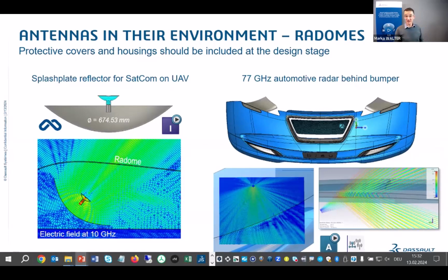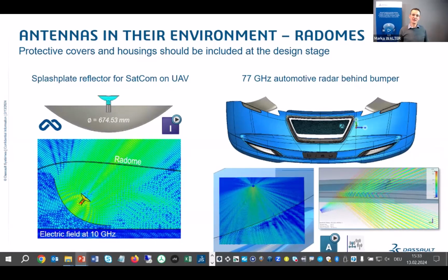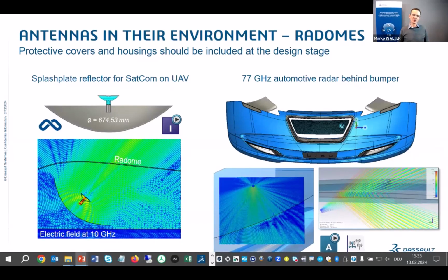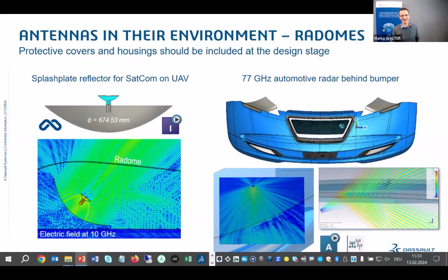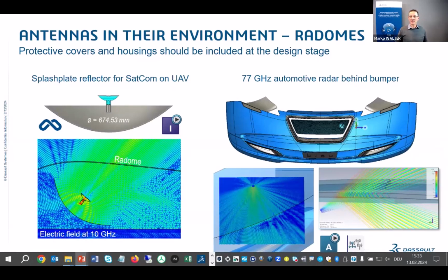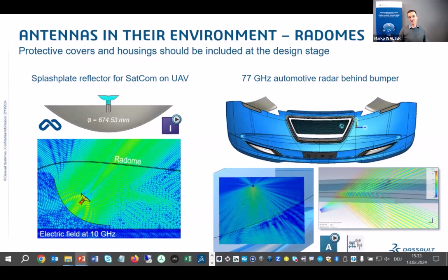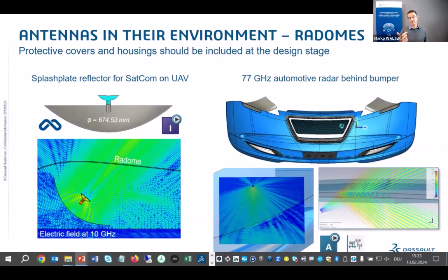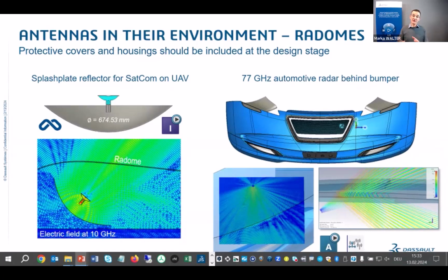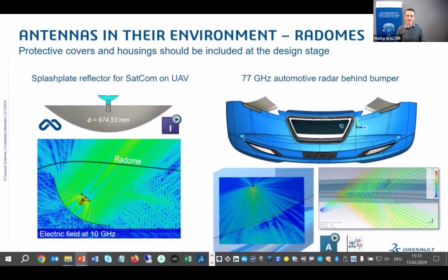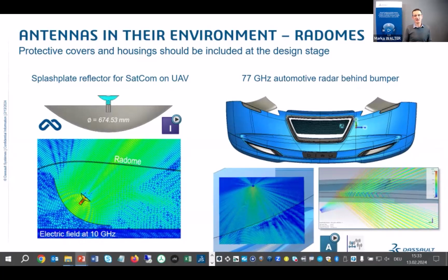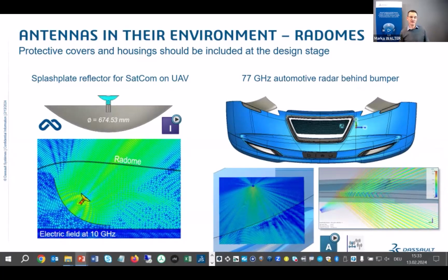We also typically, when we're placing antennas, need to protect them from the elements. So from rain or snow, hail, temperature, even lightning. And as such, the shaping of that antenna, or at least of the cover, its structural behavior or characteristics, its aerodynamic properties become important, and they act as a constraint for the antenna design. They influence the design of the antenna, and you might have to do a co-design of that radome shape and the antenna itself. So here, again, two examples.